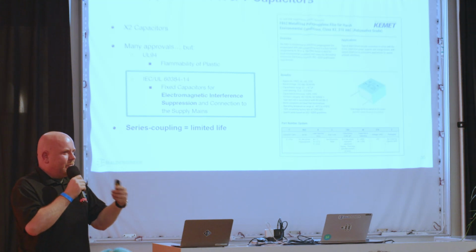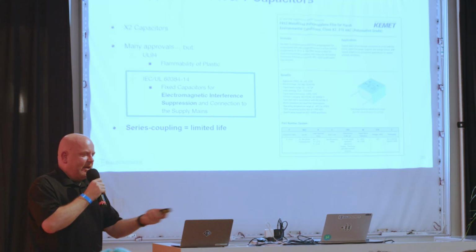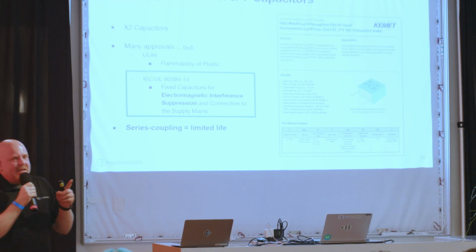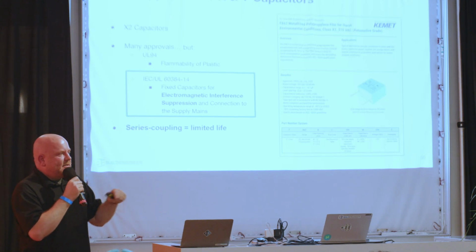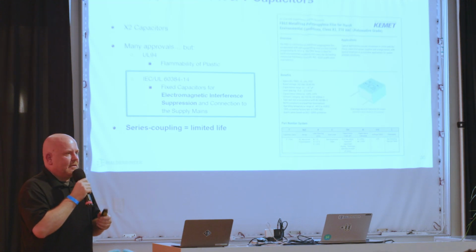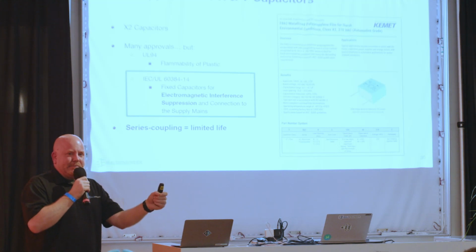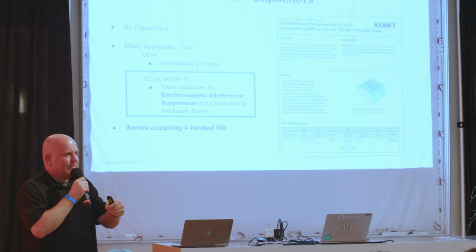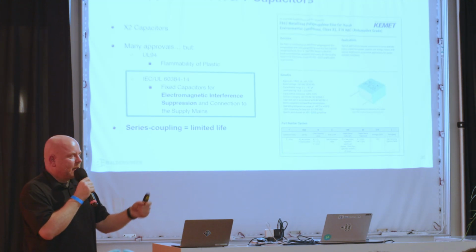So it's like a fool's errand to say, oh, this is UL approved, so that's why we're going to use it. UL won't approve the design because it's incorrectly used. Also, and this is a dirty secret that big capacitor doesn't want you to know, when does EMI testing occur for a product? What part of the production cycle? Does it happen before the product ships or after? You get your FCC cert before the product ships. Nobody cares if the EMI filter stops working 10 years later.